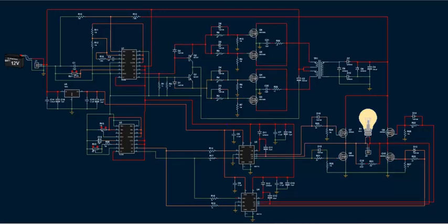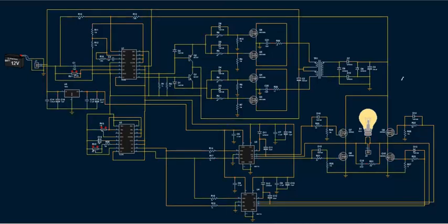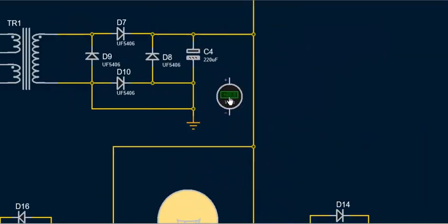I will start by placing DC and AC voltmeters across the stage's outputs. The first stage outputs 310 volts to 340 volts high voltage DC output from the high frequency signal generated by the first TL494 together with the rest of the first stage components.